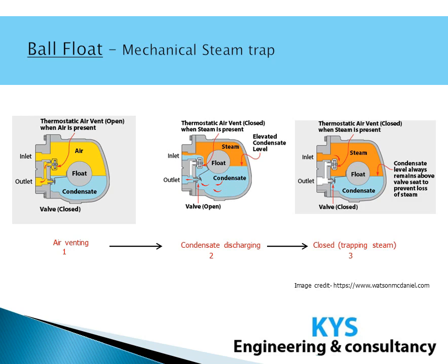The thermostatic vent valve remains closed until air and non-condensable gases accumulate during the normal running operations and cause it to open by reducing the temperature of the air steam mixture, because as soon as the air and the non-condensable gases mix in the steam, it reduces the temperature of the air steam mixture, and then the thermostatic vent valve opens and discharges the air and the non-condensable gases.